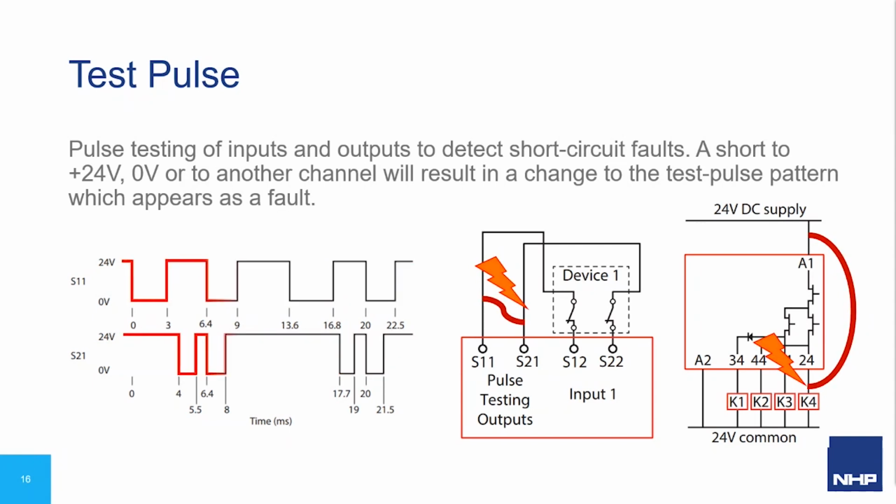For high-risk applications, we're likely going to be using redundant control signals. So the test patterns between the two channels can be made unique to each other so that if they ever come in contact, both signals will mix and become an invalid pattern. The safety monitoring relay detects this and trips as a cross-channel short fault has occurred.